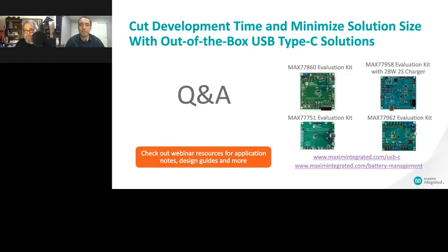All of the USB Type-C cables are required to be USB certified. And second, the basic current capability of the cable is 3 amps. So with any system, if you have a power delivery system which goes up to 20 volts on the input, you can get 20 times 3 amps, which is up to 60 watts of power. The standard USB cable will provide that.